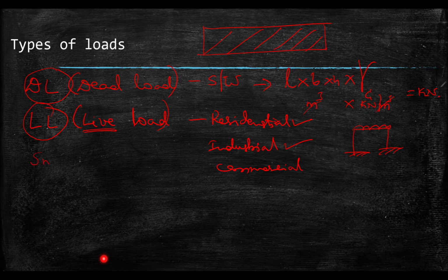Then, based on the location of the structure, we will be having the snow load, the earthquake load, and if the structure is constructed in hilly areas or is a high rise structure, the wind loads are the main important things. Then we need to go for the blast loads if the structures are hazardous buildings. So all things will be taken care of when we are going for the type of loads.